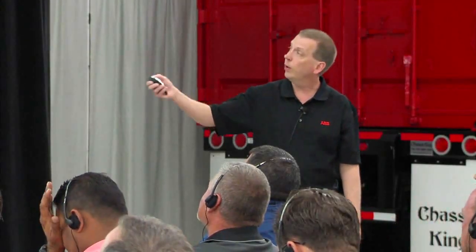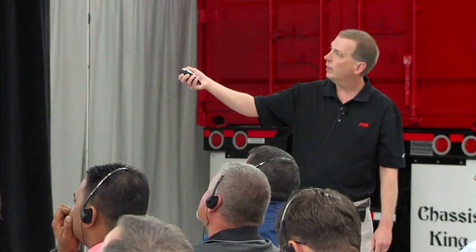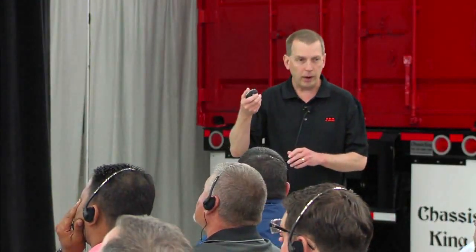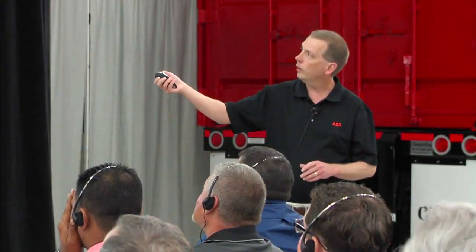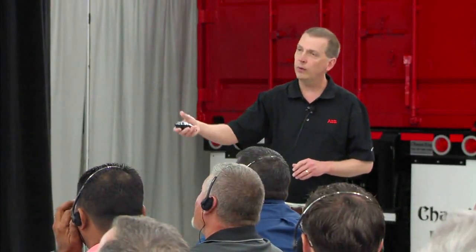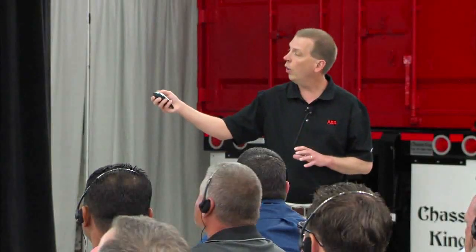And the way those push buttons work is that the start input is a normally open contact. What does that mean? Well, it means that the contact is held open by a spring. Normally it's not conducting at all. When I push the button, it makes that contact, and then when I release the button, it opens that contact. It's normally open. The stop button, the other button, is a normally closed button. And the spring holds the contacts together. I push in the stop button and it opens this contact. When I release it, it recloses it.